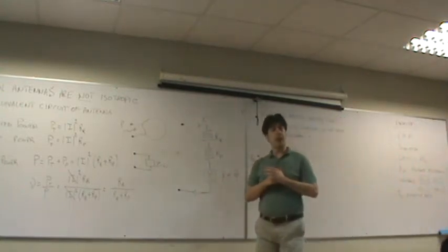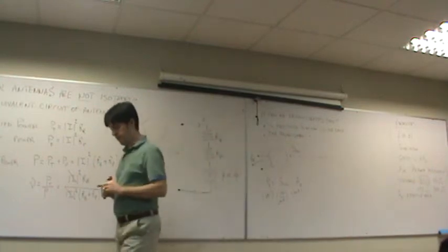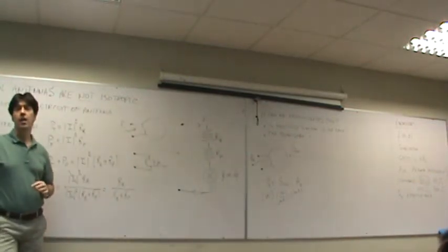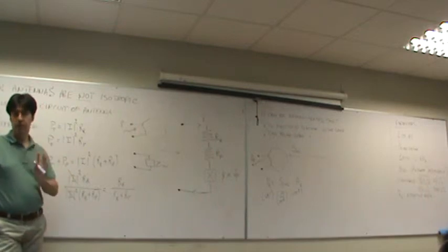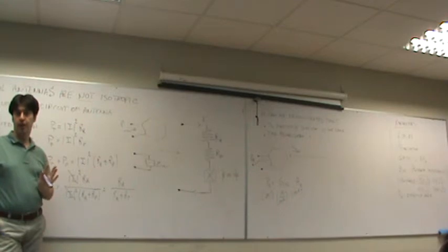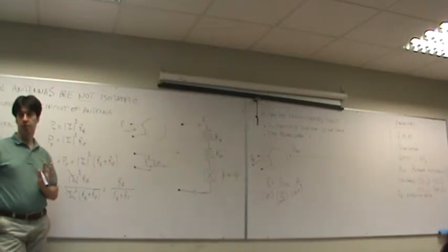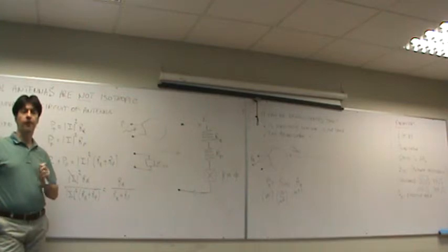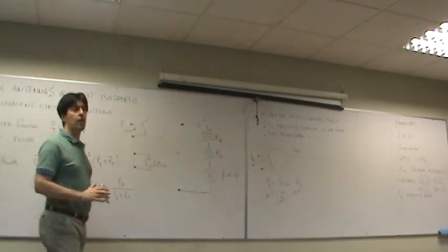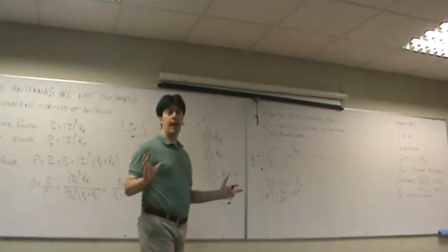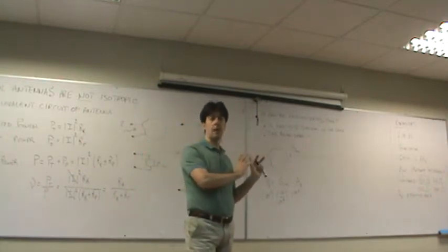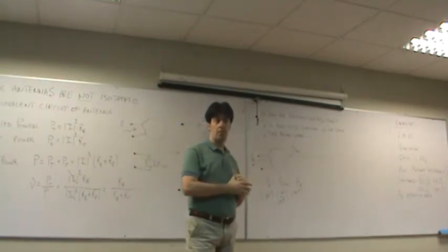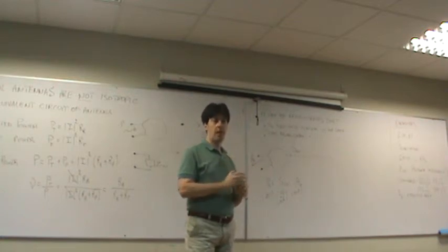Please note that the effective area, this is important, the effective area has nothing, in principle, to do with the geometrical area of the antenna. Okay? Unless in very, very specific cases, the effective area is not related to the geometrical area of the antenna. It's an electromagnetic parameter. It's not a geometrical one.